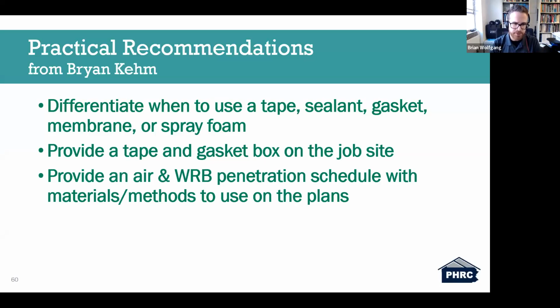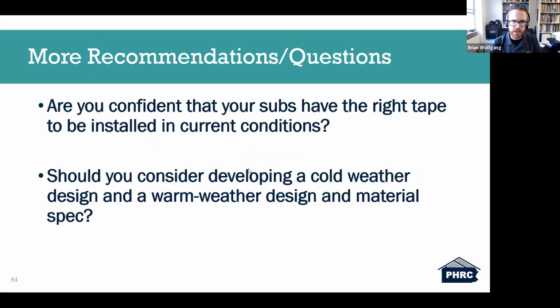And then that third recommendation has more to do with the construction drawings. Provide an air and water resistant barrier penetration schedule with materials and methods to use on the plans. Your construction drawings are a primary way to communicate your design intent. And if you really want to make sure that your design intent with specific manufacturers' products is being used, make sure you're explicit with it on the plans. A couple more recommendations here before we finish up. We're at 2 o'clock here.